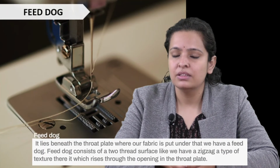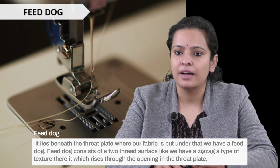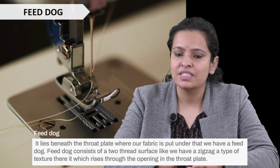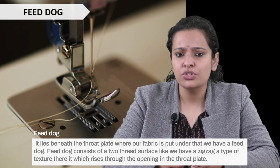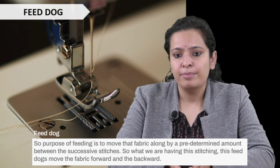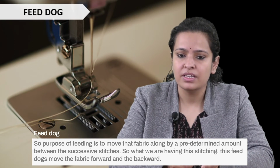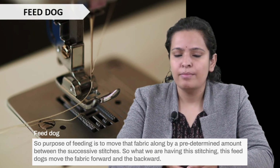Then we have the feed dog. Feed dog lies beneath the throat plate where our fabric is put. It consists of a toothed surface, like a zigzag type of texture, which rises through the opening in the throat plate. The purpose of feeding is to move the fabric along by a predetermined amount between successive stitches. While stitching, the feed dogs move the fabric forward and backward.